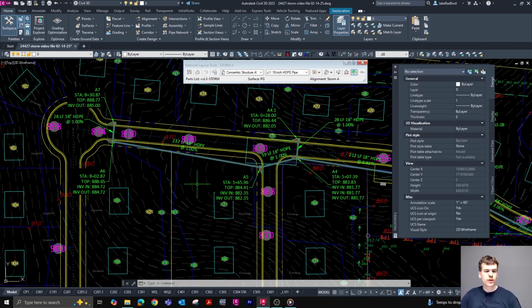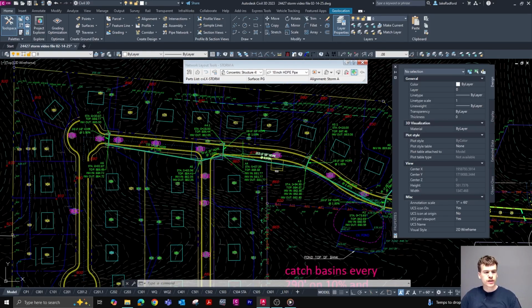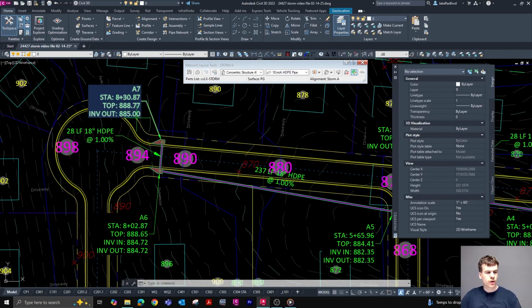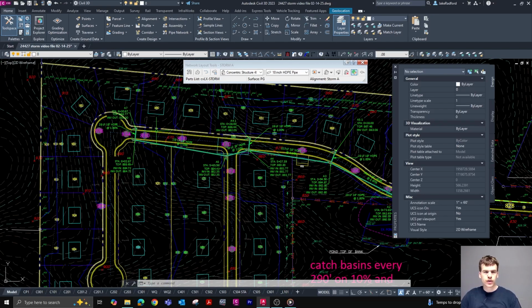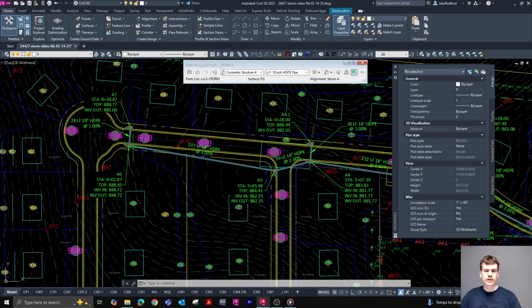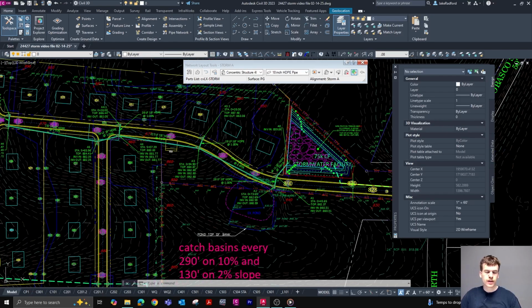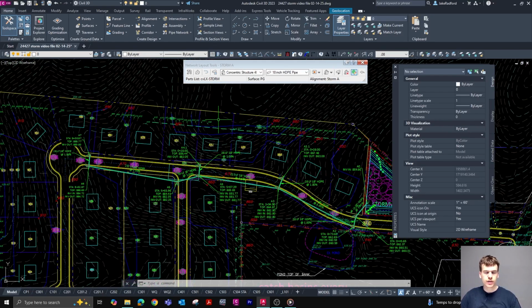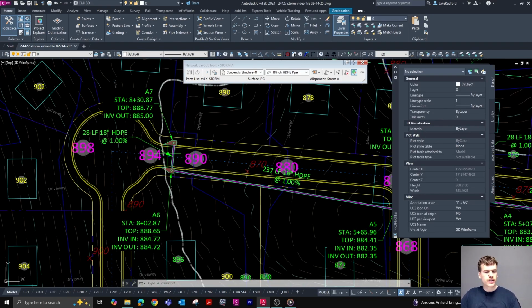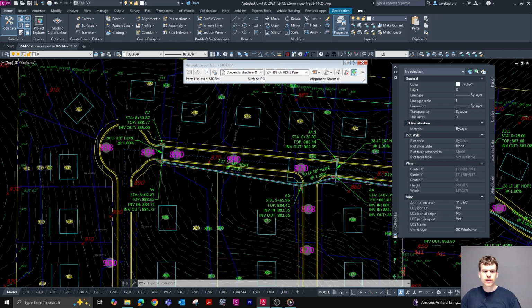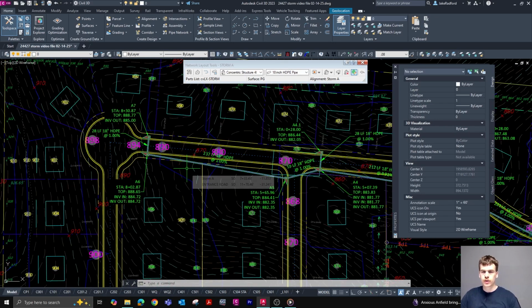So between the last video and this one, I just continued that process shown in the last video, where we started from a certain point, a constraint, and then we designed with a 1% slope from our pipes all the way down. So we started from upstream and worked to downstream. Again, that's against our typical protocol, which would be to design from downstream to upstream. Every project varies. You always want to design from your constraints, but in this instance, we designed from upstream to downstream to demonstrate the relationship between negative and positive values for slopes and how that can change the way that your pipes and networks are designed.